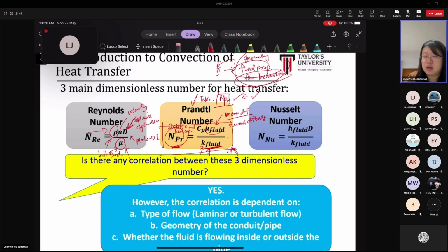All right, so then as for Nusselt number, the Nusselt number is the convective heat transfer coefficient multiplied by the diameter. Again, it could be diameter or the length, right? Depending on what you are dealing with, let's say the sphere and the cylinder, then we'll be using diameter. L is for plate. So Nusselt number equals the convective heat transfer coefficient multiplied by the diameter divided by the thermal conductivity. So it's as if this is a ratio of convective transfer to thermal diffusivity, right?